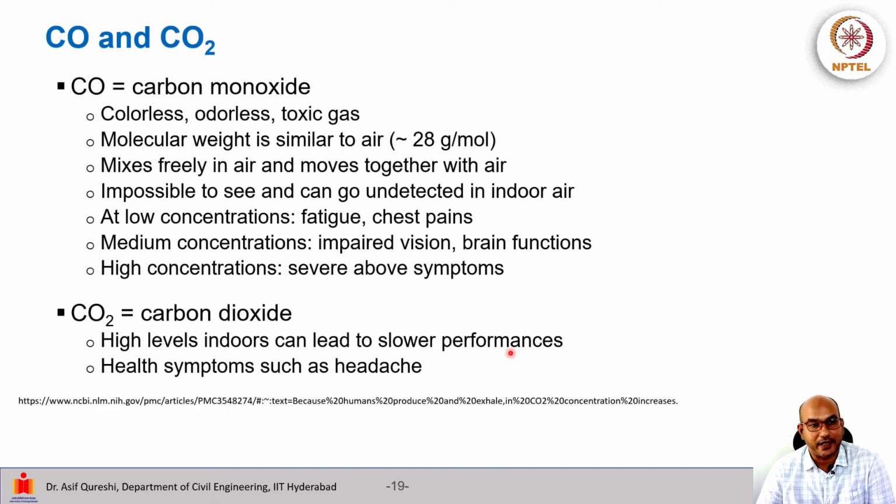Then we have carbon monoxide, which is a colorless, odorless and toxic gas. It's quite similar to air in its molecular mass, which means it basically mixes freely in air and moves together with it. Wherever air is going, CO will go. It's impossible to see and can go undetected in indoor air. At low concentrations, it causes fatigue and chest pains. Then it will start to impair brain functions and vision at medium concentrations. And when we arrive at high concentrations, we will have very severe versions of all these symptoms. So CO is a very dangerous gas.